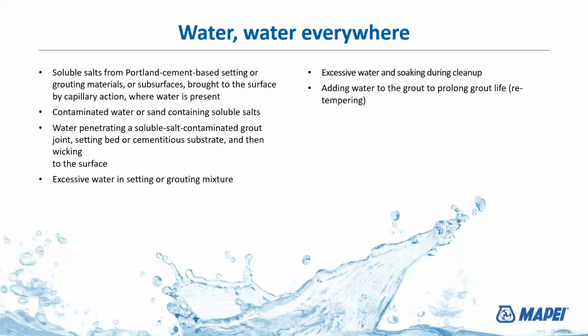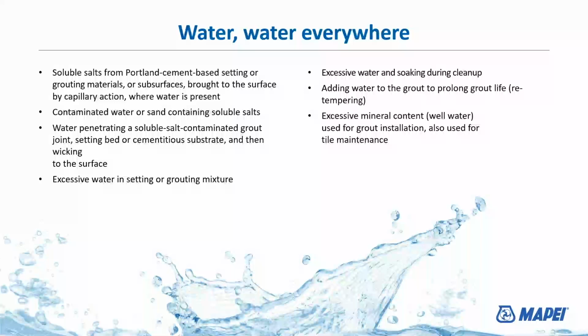Mineral content in well water that's untreated. People ask all the time, can you use well water to mix grout? And the answer is yes. If the water's been treated correctly and is considered what's called potable water, and if the water is coming out of the ground and filtered and treated correctly, there's no reason well water can't be used in a grout mixture. City water comes from wells. All of it comes from wells. And then the water is treated and processed. So yes, well water can be used.